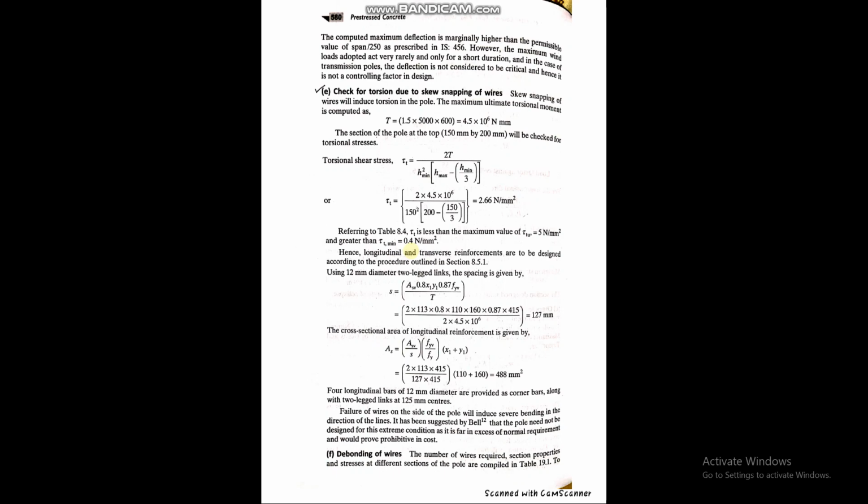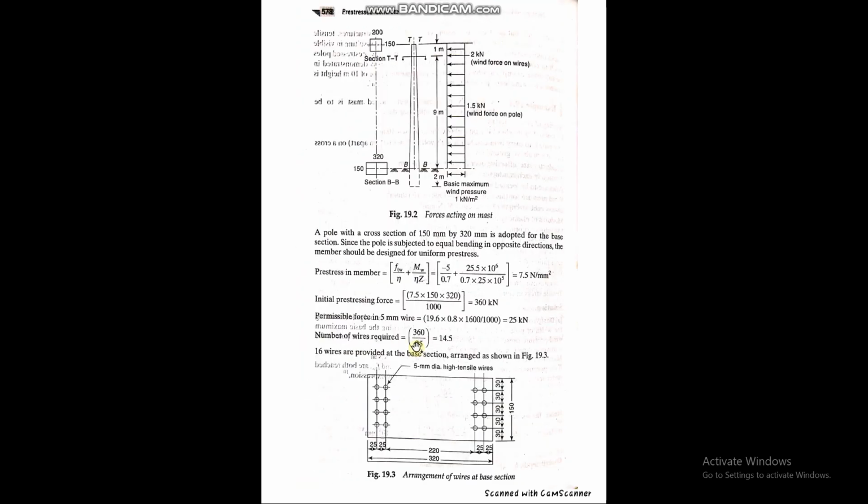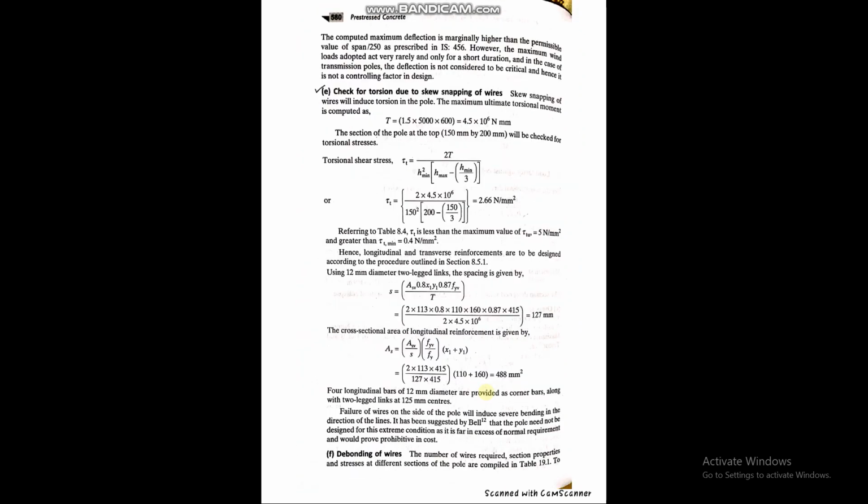All right. So in this case, what is going to happen? Basically, you have the tensile wires like this. So at the corners there will be longitudinal bars that will be provided to support a transverse reinforcement in the form of stirrups. All right. So to resist against the torsion, you have to give longitudinal reinforcement, and that will be supporting the stirrups throughout.